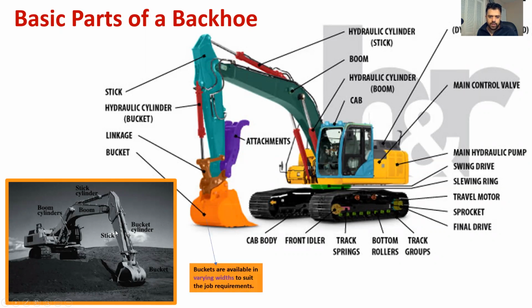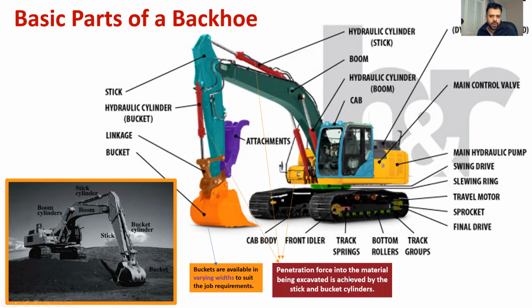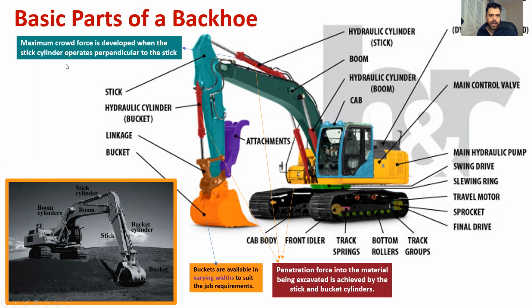That's how it works. So buckets, like I said, are available in different widths depending on the job requirements, and the penetration is controlled using these cylinders. Okay, so the maximum crowd force is developed when the stick cylinder operates perpendicular. Okay, so when this is perpendicular, you can exert the maximum force to the ground.